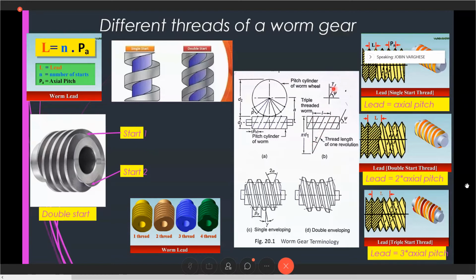So we can see that one, that is the vertical. When we take the vertical with this angle, we get this lead angle. And in fact, this is the helix angle. Here we are using the helix angle as beta. So here, beta, when you see the axis, the helix, in this one you can see horizontal. Vertical gives the lead angle, horizontal gives the helix angle, and there is another called the pressure angle.